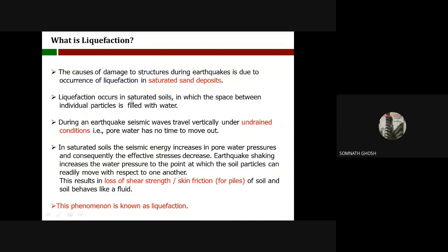Liquefaction occurs in saturated soil in which the space between individual particles is filled with water. That you all know. In any soil media, between the particles, it is always filled up with water. During an earthquake, the seismic wave travels vertically under undrained condition, right?